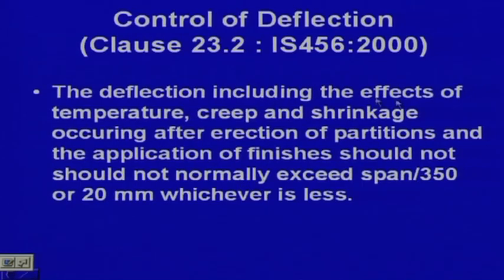The deflection including the effects of temperature, creep and shrinkage occurring after erection of partitions and the application of finishes, please note.